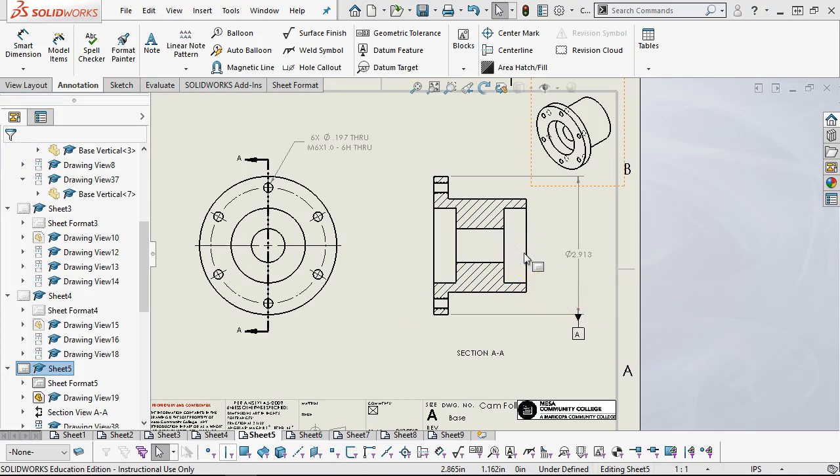All right, and then really from the position, as long as those holes are in line, I don't really need any kind of flatness and parallelism. I do need position on that width, or a position on the holes, and a max min on the width.